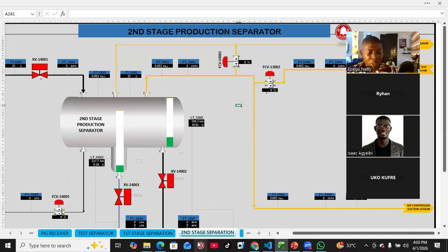And then one of them is carrying out what they call management of change. It's very, very important. And that management of change is to safeguard you as a control operator, because you're going to be having your documents stating why you are carrying out that bypassing. Okay, the process guys, the safety guys, they are going to carry out a risk assessment, to ascertain if they bypass that particular alarm, what is going to be the effect, right?